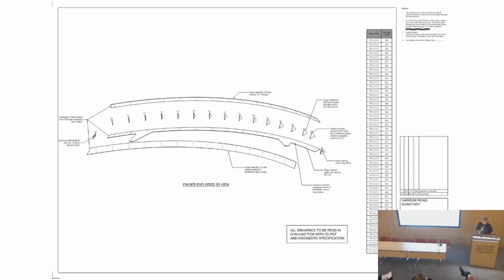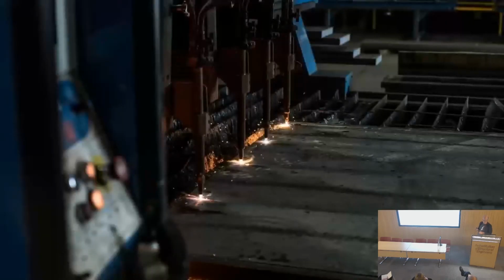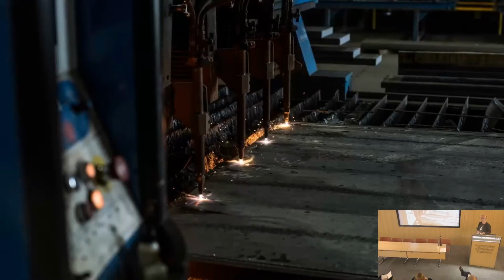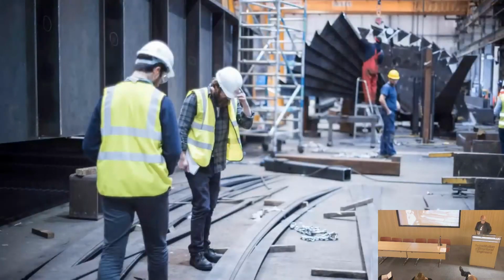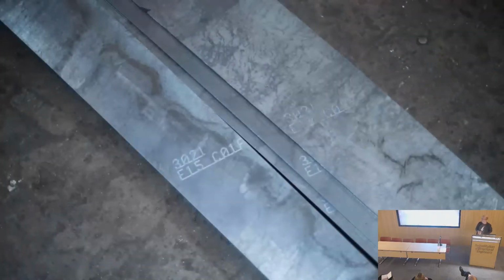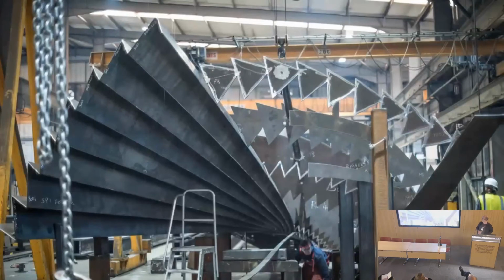And each of those fingers is designed so the surfaces weld together and form a structural triangular section. One of those is planar, so it can sit on the floor of the workshop, and we can set the thing out easily. And then these two outer ones curve together, and then it has bulkhead. That is all made possible by a technology that's been in fabricators' shops for years, which is CNC-controlled plasma cutters. And they cut the steel sheet. You end up with lots of different shaped, banana-shaped pieces of steel that all have to have the right number on, otherwise it's complete confusion.